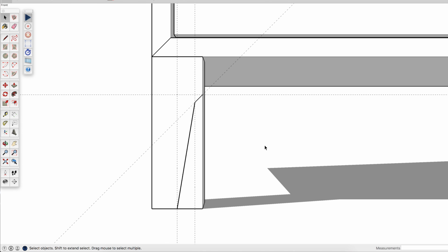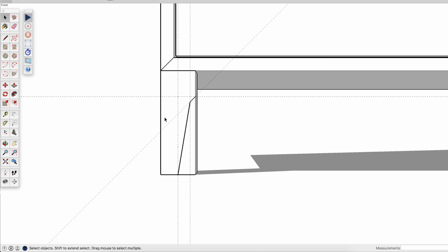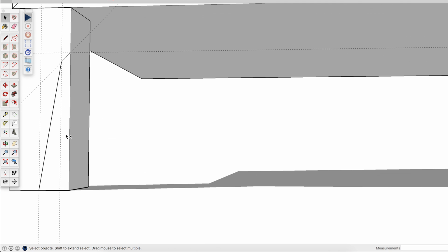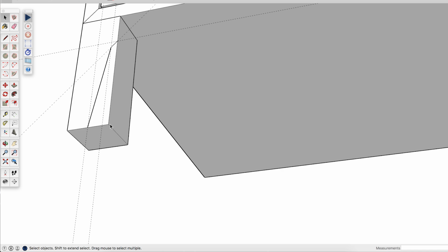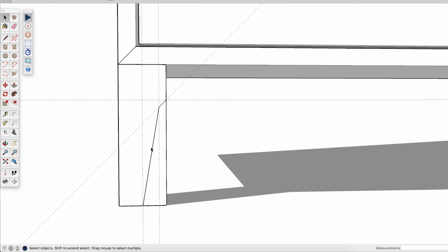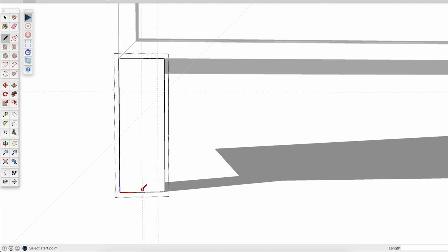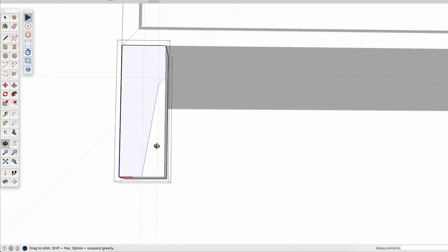This sort of a shape. But I want it to be straight or flat against the plane of the bookcase on this face and on this face, and then have this kind of taper on the inside faces. So the way that you do that in SketchUp, I'm going to back up here for a second. I'm going to go into my component and start editing. And I'm going to just draw that exact same shape. So now you can see the two faces that I have.